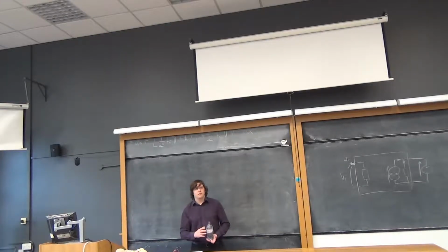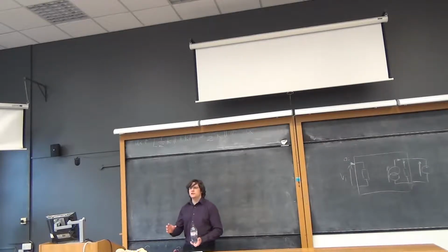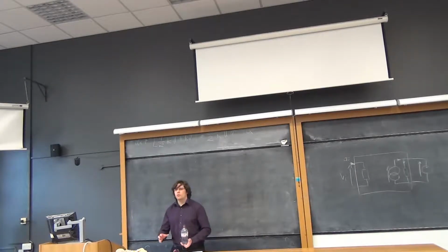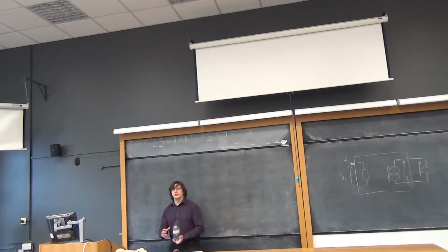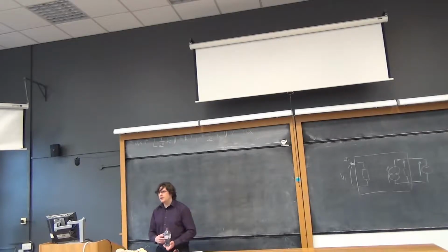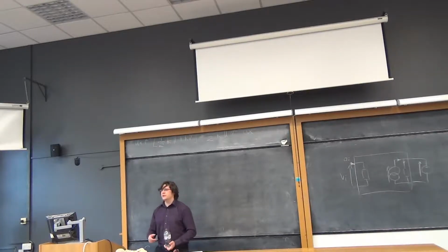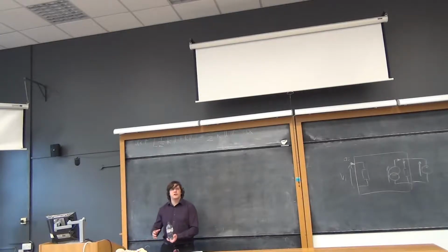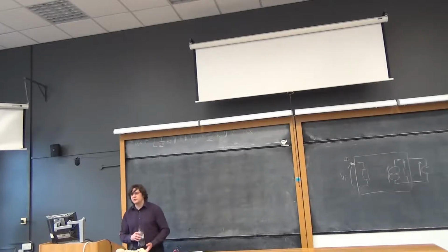Another way of thinking about that is that some of the power that we want to transmit into the amplifier will be reflected as well, so we won't be able to get all of our signal into our amplifier. This will be covered again, and it doesn't come into this course or any course that follows it for a couple of years. But when I say use below 30 megahertz, the reason is you cannot really use this kind of amplifier with travelling waves. If you're interested, feel free to Google it.